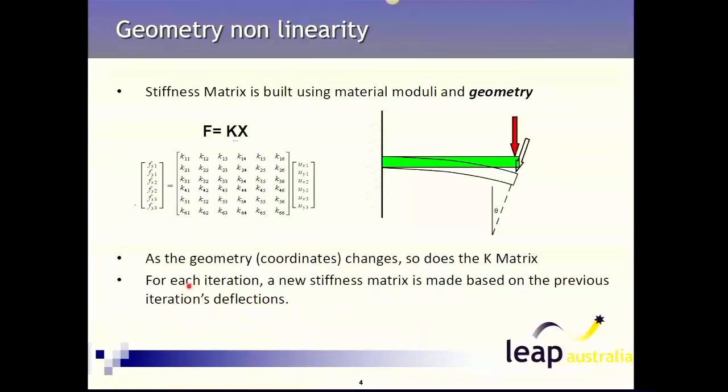Okay, in terms of visualising this, instead of us just talking about one single value, here we've got a stiffness matrix on the left-hand side, and this is our structure. These individual stiffness terms come from the initial positions of the nodes. As the nodes move and rotate, usually if an element rotates by more than 1 or 2 degrees, then these stiffness terms are no longer accurately representing the stiffness of the geometry. Each one of these terms you can think of as the effective stiffness at each node. Some of these will be shared because there'll be shared elements at some of the nodes.